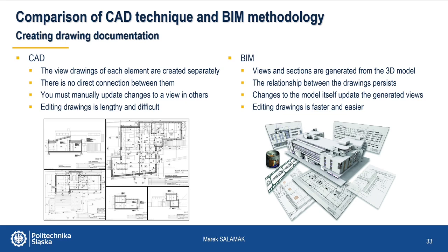In the case of the BIM methodology, views and sections are actually generated automatically based on the BIM model. There is a full relationship between the drawings generated in this way. Model changes update the generated views automatically.